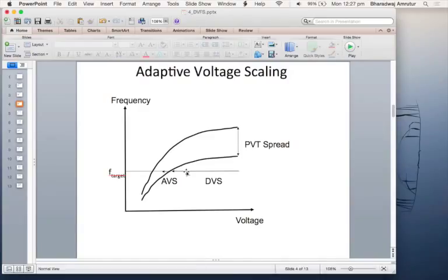You run Spectre or HSpice or Eldo, any of these circuit simulation tools. You take your circuit and you simulate it and find the delay of the critical paths. The problem is there could be many critical paths, and that is where this kind of analysis becomes difficult to get the F2V curve. So this is kind of challenging. If it was a small circuit, then you can easily find this F2V curve by just running at different voltages, just seeing what is the max speed at which it runs.